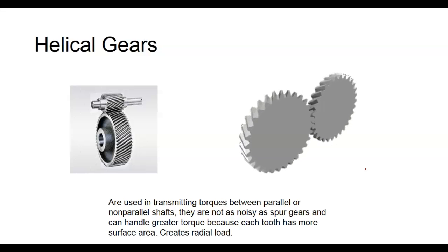So it's like in that gear video, he had the two bigger gears and one gear in the middle, yeah. And he changed it out to a bigger one, and he did all the math, and it actually canceled out. It was a pretty neat thing. So yeah, the idler wheel basically has nothing to do with whether it's a torque multiplier or a torque divider. All it does has two purposes, and that's what? To change the spacing between the driven and the driver, or to make the driver and the driven rotate in the same direction. So that's the only reason we use it.